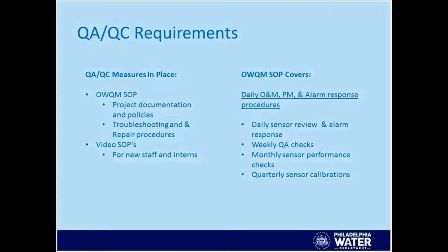It also includes troubleshooting and repair procedures, not only for the instrument technicians, but also for the engineering staff. So we have flow charts where the instrument tech can follow the sequence through the flow chart, and then he gets to a point where it's okay, I need to get an engineer involved, and that's where their responsibility ends, and the field engineer has to come in and take over from there.